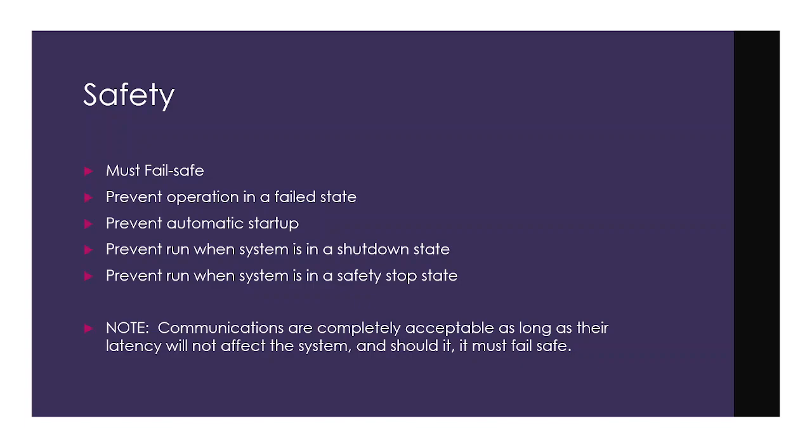Obviously, it won't have any type of automatic startup. It'll require some type of a manual startup, manual override, resetting all the e-stop buttons, or pull ropes, light curtains, etc. And then you'll have to trigger some kind of power on or reset function. Yes, you can do automatic systems. That's not entirely the point of the automatic startup. The automatic startup means that when we power on something along those lines, we're going to require some kind of power on.